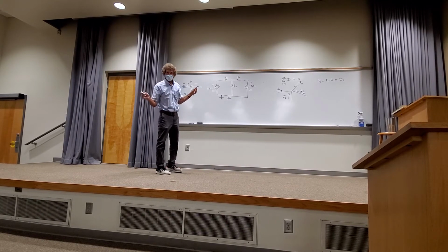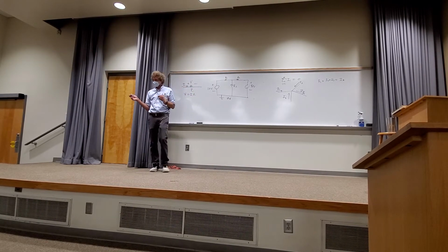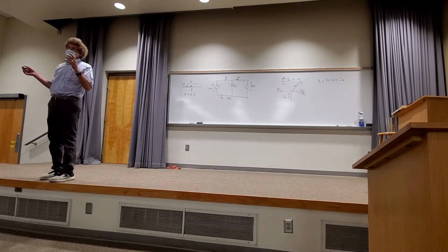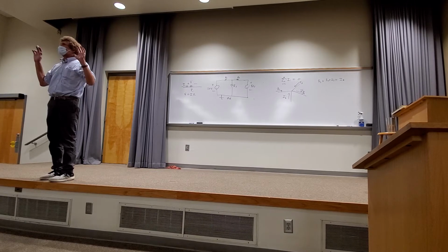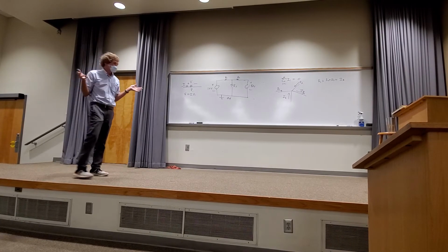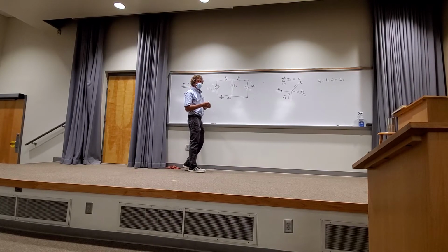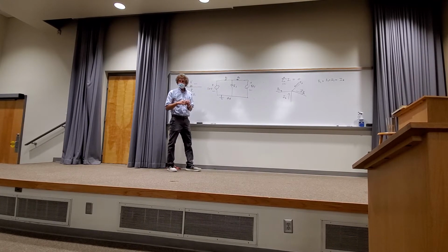The term for this in the book you have for the course is nodal analysis, but it's based on Kirchhoff's current law. You don't need to remember the term. What it says is this: all the current into any junction is the current out of it. Do y'all follow me? Now the way we apply this law is such.